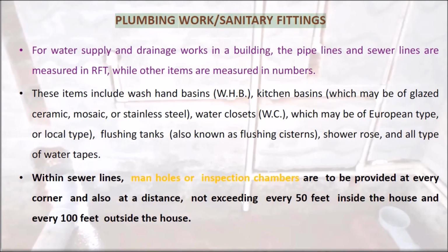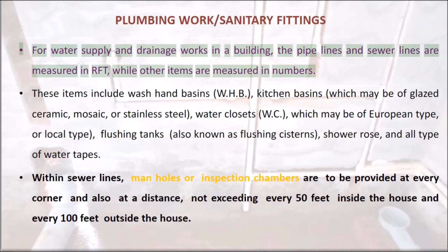Plumbing work/sanitary fittings. For water supply and drainage works in a building, the pipelines and sewer lines are measured in RFT, while other items are measured in numbers.